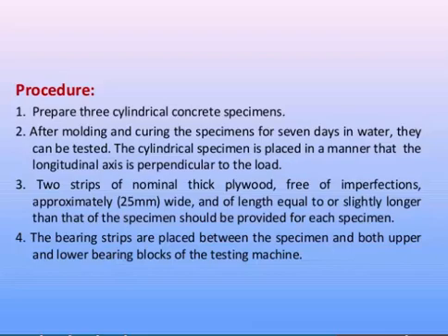After taking it out of the water, the samples are wiped off, and then draw diametrical lines on the two ends of the specimen to ensure that they are on the same axial plane. This is an important step. Record the weight and dimensions of the specimen.